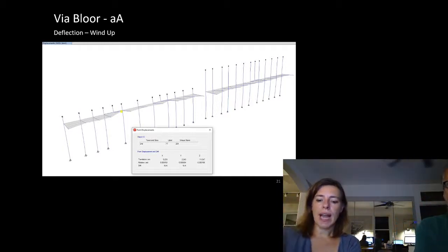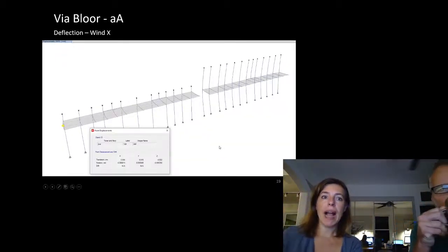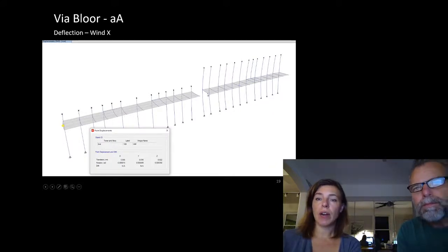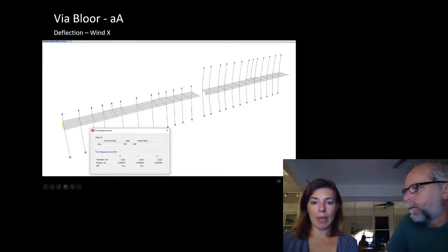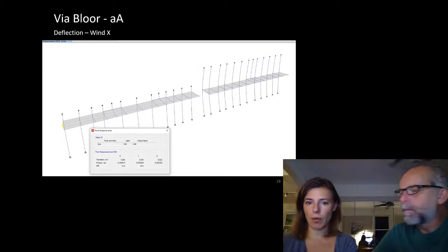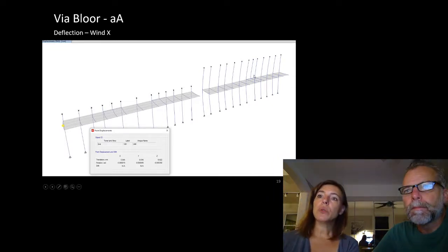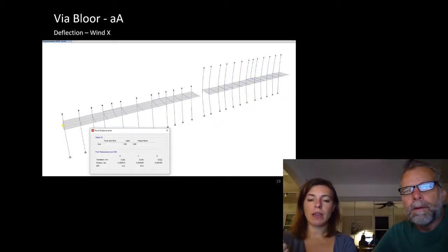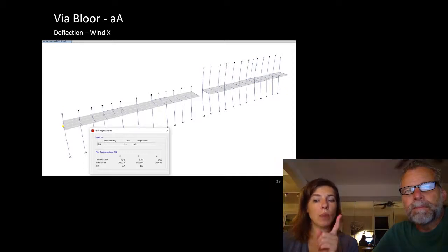The other question they had asked, if I just go back to that racking one, they had asked about applying a lateral element here. But to make it work, it needed to be moment connected. Just applying a pinned element in between them did nothing for racking for us. And the values were so low that when I did the analysis, you could see we had very small out of plane movement of these columns with one small modification.